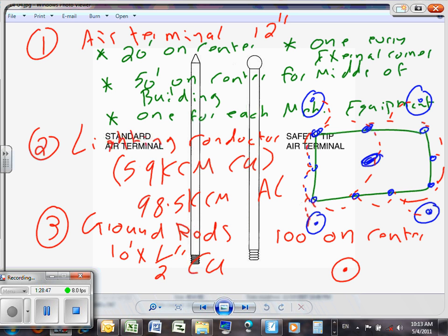I want to let you know, Camille, my friend, there are detailed lightning CAD drawings that we gave you. Please go to the lightning file, which has detailed CAD drawings. Here's what I hope you guys will do: import them in a drafting view in Revit as is, call them detailed lightning E14, E15, E16, and just dump them in the back of your book as lightning details.